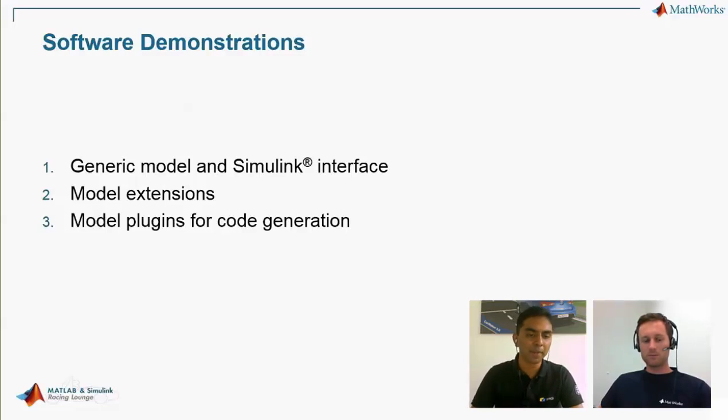This means if you have your own model in Simulink and you would like to plug it in with the CarMaker environment, how to extend the environment and bring in your own models. This is shown in the second example. Further moving on, whatever you did in the second step, the model which has been extended, how to generate code out of it and port it to special ECU targets or special microcontroller targets, etc. So these three subjects are what I've planned for you, and I think this is going to be interesting for the students who are looking forward to such a demo.